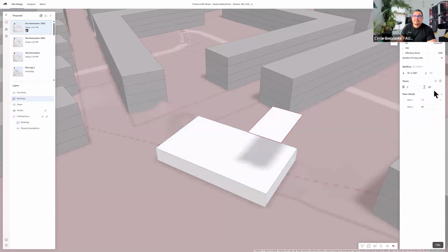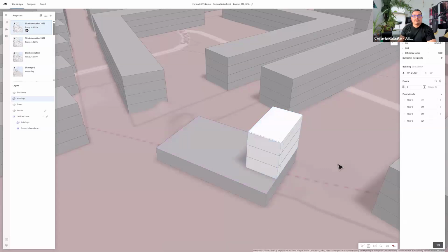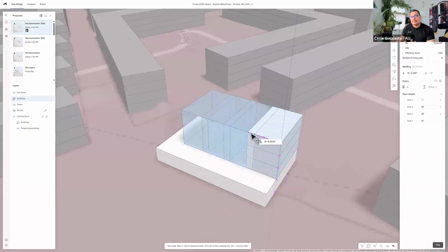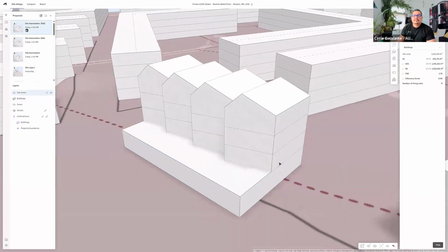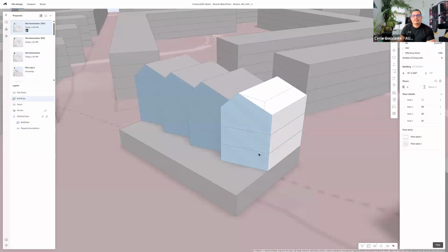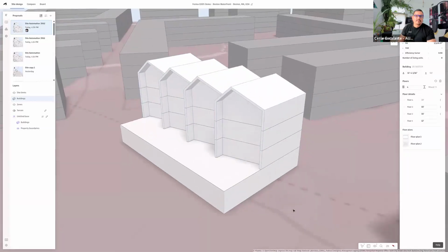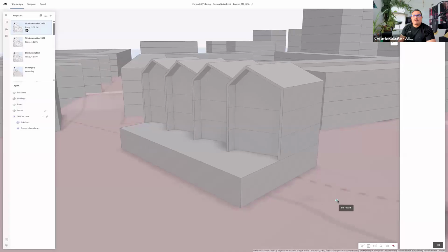These unitized towers can be arrayed as a group and be edited as a group. And the beauty of doing it as a group is that you can start using push and pull operations to add greater detail to the building representations. You can add overhangs using push extrusions.